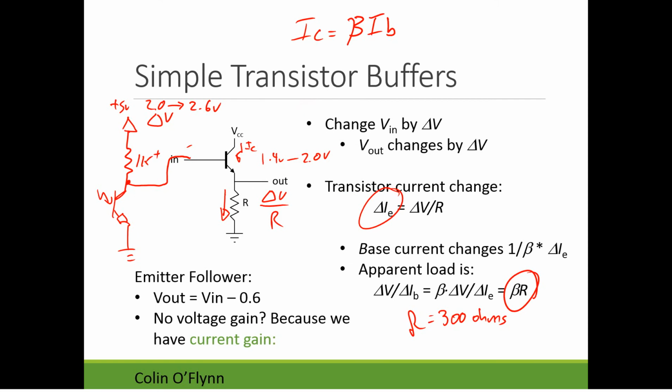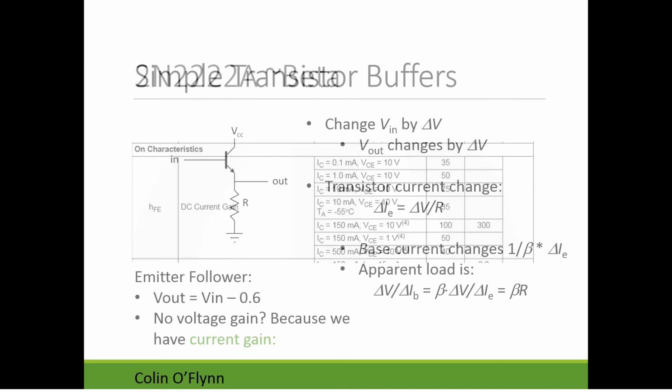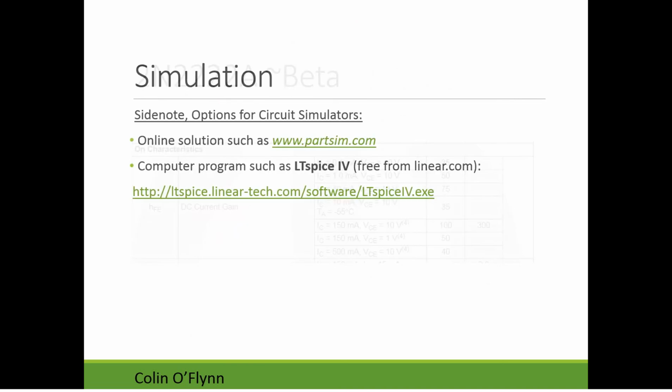It will only work within a certain voltage range at the input, for example. A circuit simulator is a really easy way to check you've set things up properly, that you have sufficient current flowing through the collector of the transistor and so on. So it's important to do these simulations.